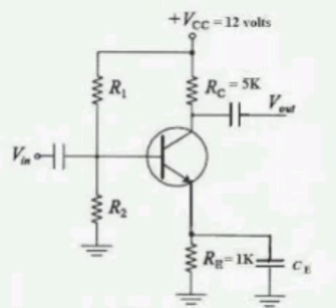Please remember, flat band voltage VFB is the gate voltage at which the semiconductor's Fermi level aligns with the intrinsic Fermi level at the surface, resulting in zero band bending.